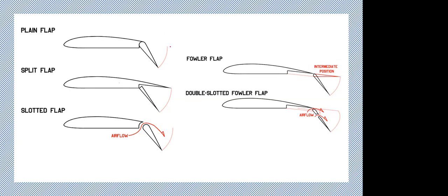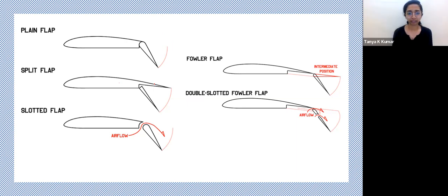I know about the disadvantage that it increases wave drag, but the advantage is that the flow will remain almost stuck to the surface till the end of the airfoil. Exactly. So boundary layer separation is delayed. Here it will not stick till the end. It increases drag. So the split flap is more often used as a spoiler. If it's completely deflected, it is used as a spoiler.